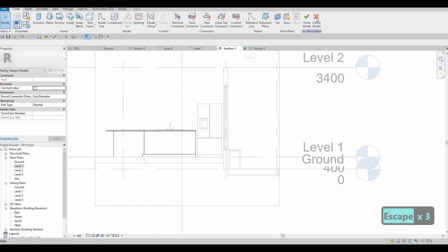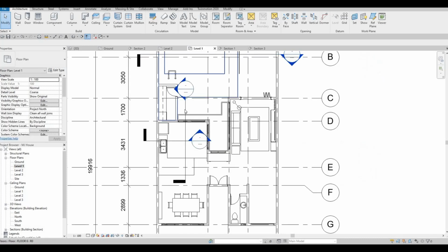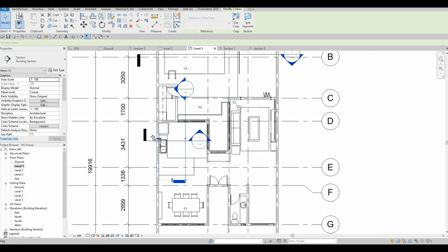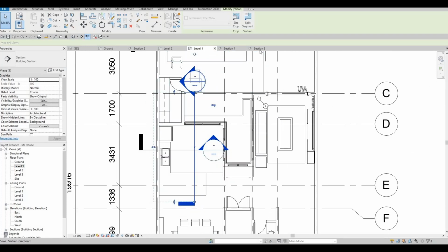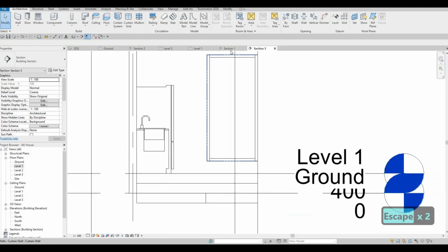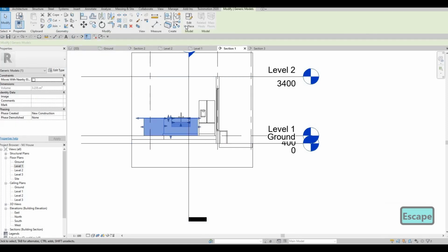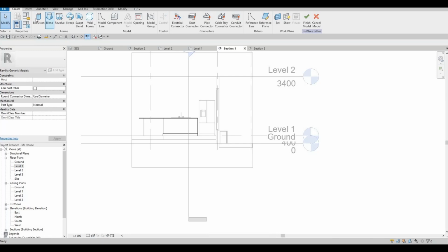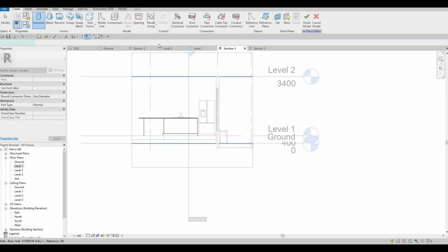So the issue with this is that the section was not overlapping the wall. That's why the wall is not showing. So now I'm pretty sure that it will show. And then we could just select this one, edit in place, extrusion, pick a plane, and then this one.